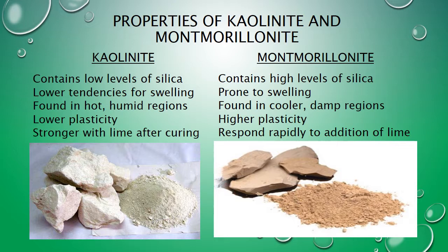The addition of lime helps decrease plasticity in montmorillonite greater than kaolinite due to its ability to help soils repel water. It also reacts faster with montmorillonite in terms of increasing strength. That said, kaolinite gains more strength by comparison after having longer times to cure with lime.